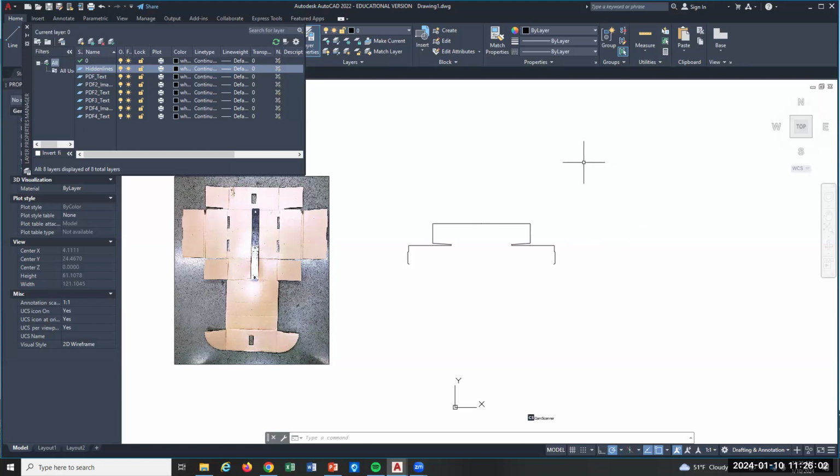All right, so today's project is just to create the two templates. Inside the two templates, each one should have two layouts, right? These two layouts should be named A size, B size, at least. And then your two templates, one's US, one's metric. Yeah, title blocks in all of them. So FYI, make a title block in one of your layouts.